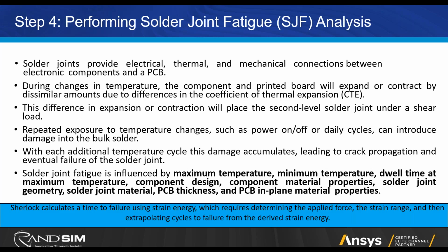So now that you've exported everything, we can start on performing the actual solder joint analysis. As you might know already, solder joints are what's connecting your packages and all of your different components to your PCB, and even sometimes providing mechanical connections. And the same way that we detailed at the beginning of the report, changes in the coefficient of thermal expansion cause shear to be applied to the solder and cracks to form.